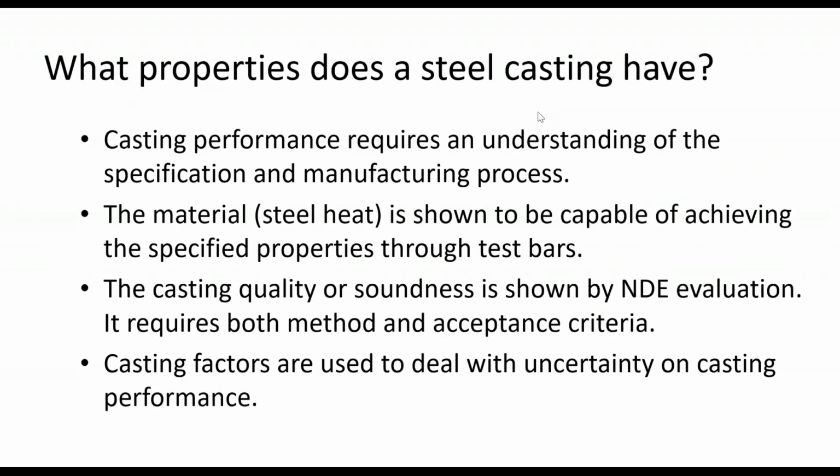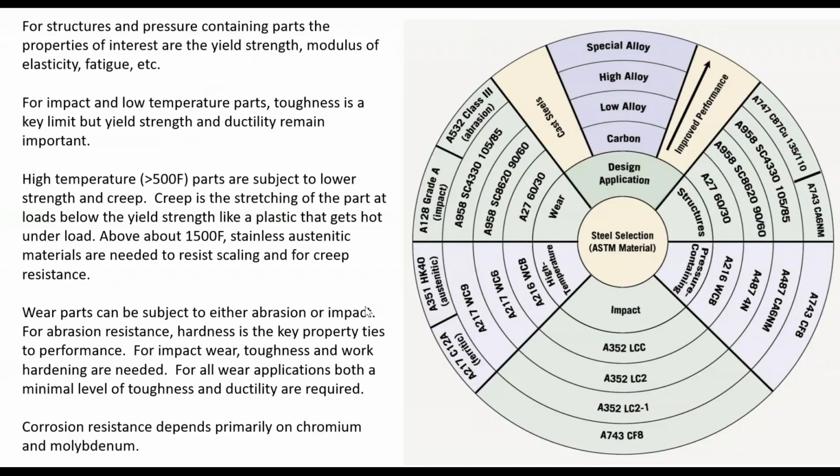So what properties does the casting have? It's both the material properties that we've talked about and the casting quality. In test bars, if the bar isn't of good quality, I throw it away. In a casting, I set that quality with non-destructive testing. So I have to design the casting recognizing that I may have some porosity in the center line and some indications on the surface. This is true of all steel products, but certainly castings are more challenging than some other products. I talked about fatigue and toughness as being limitations, and while they're related to yield strength, yield strength doesn't predict them exactly. And so here you have the fatigue stuff, here you have the impact stuff.